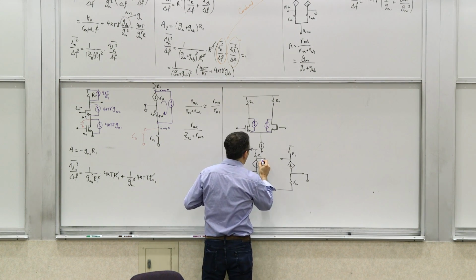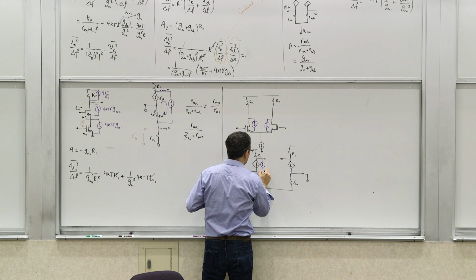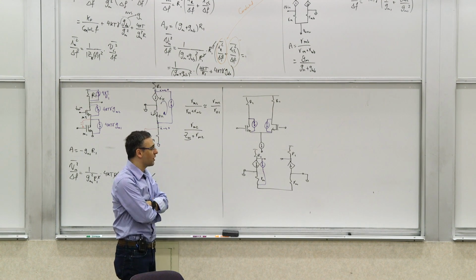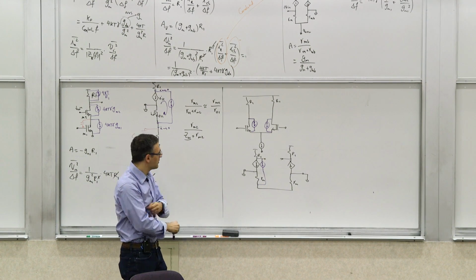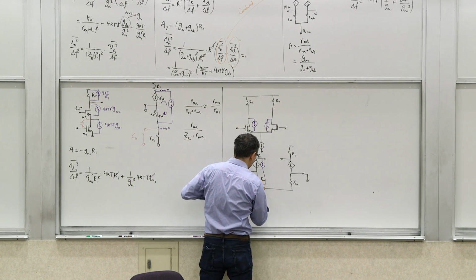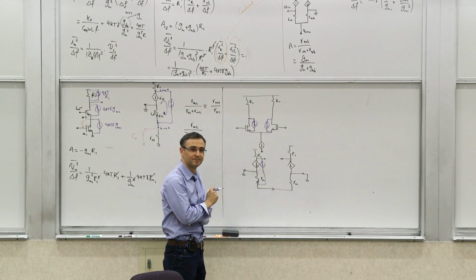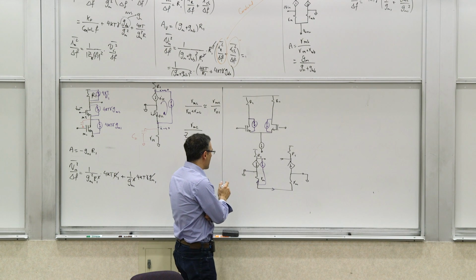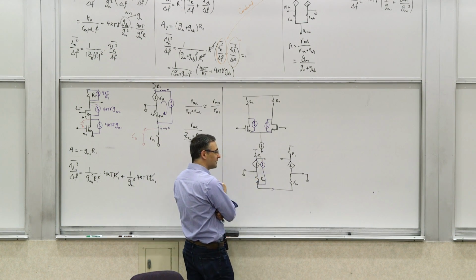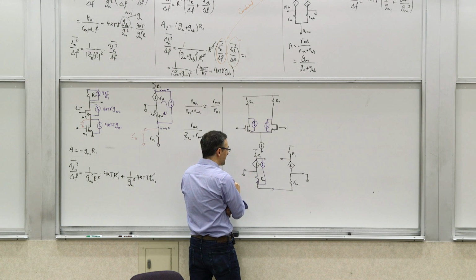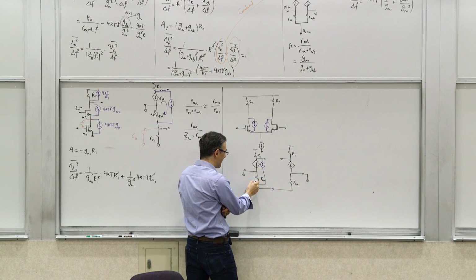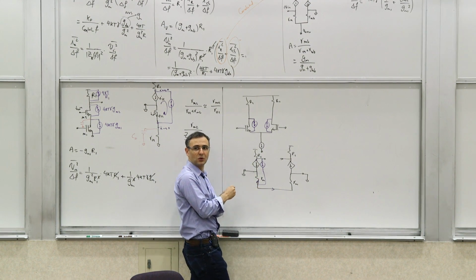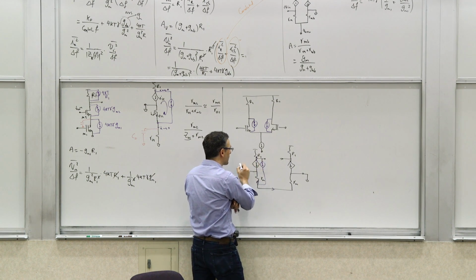So if I put a noise source here, how would it divide between the two Rm's? Evenly, right? So what happens is that half of this current goes here, and half of it goes there, right? And this half that goes there, it reflects up here. So what is left is the other half, right? Because this half is the same half. This current source is reflected. So what is left is the other half. So the other half goes into the R.